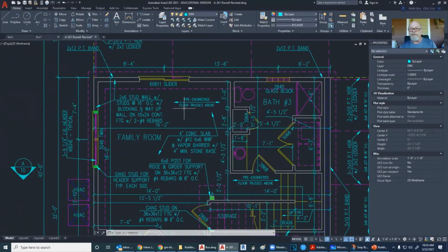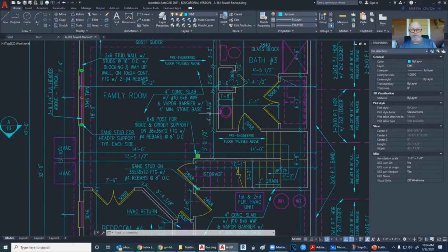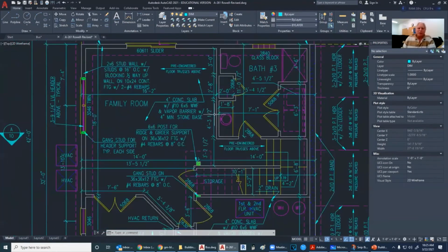Okay. So what is the smallest increment that you design to in a house? Well, which aspect? What are you referring to? Okay. So when I'm going to lay out this house here, you mean the room size? I mean, room size, placement of walls. For instance, I try to stay within 6 inches myself personally, but I learned all this before I took his class. I mean, nothing less than 6 inches. But I try to stay on a 1 foot or even a 2 foot grid because of drywall.